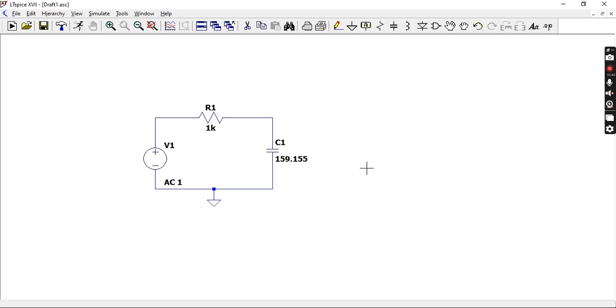So now, filters are frequency selective. A low pass filter specifically allows frequencies to pass through from, let's say, 0 to the cutoff frequency that you specify. From the cutoff, everything above that will be taken out, or it will be attenuated, or reduced in amplitude. And that is what we expect to see here.